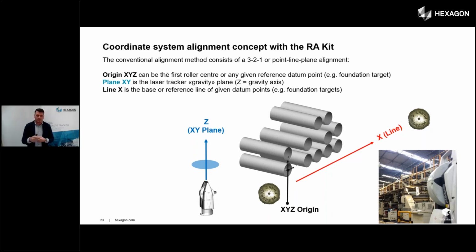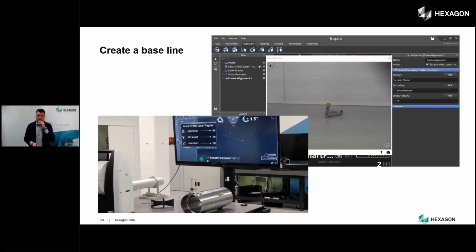So you see also here the measurement points, which can be pointed with the base plate, and then we have the coordinate system in the very first axis. This is our origin then, and then we have, very important, the x and the z-axis, and the y is a little bit less important in this roller alignment application.